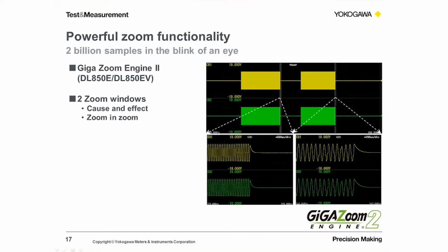And as you will see, using the other tools, the measurement tools we will be describing, we can then make measurements between those 2 points and accurately determine and look at cause and effect between channels. Something happens on one channel to cause and effect some seconds, maybe even minutes or hours later somewhere else. So we can do precise measurements between those 2 occurrences.